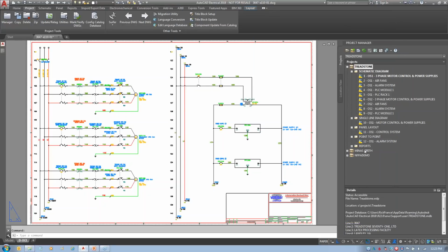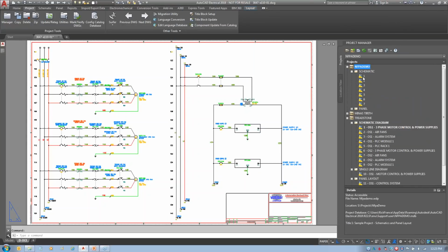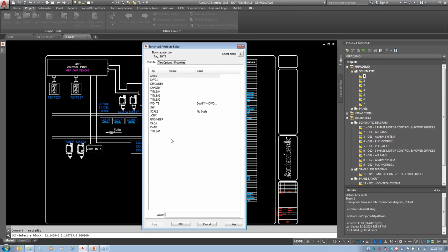However, if I open that drawing, right here, one of those drawings for that demo, I'm going to double click on the title block. There's that attribute. It wins. Even though they're using the other method, they have a 256 character limit in their title block because of that attribute. And it's in every drawing of this project. It's in every drawing of their templates. It's in everything that you get from those demos from Autodesk, and a lot of people have it.